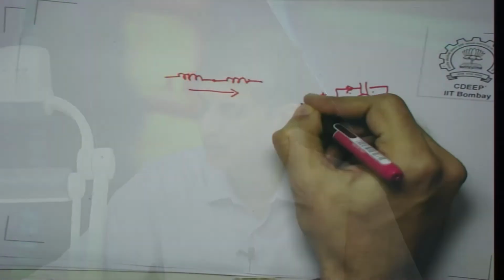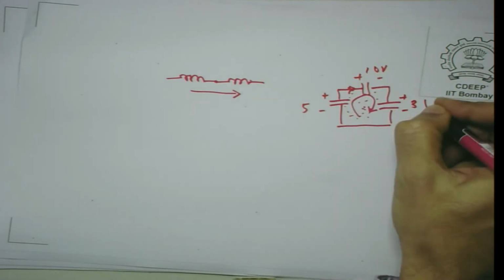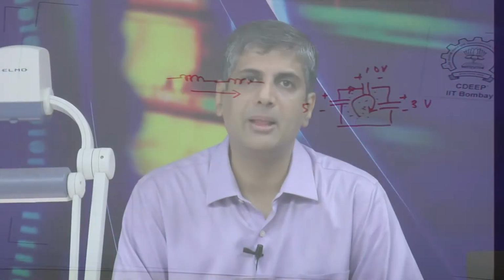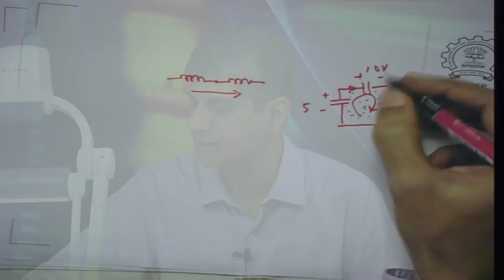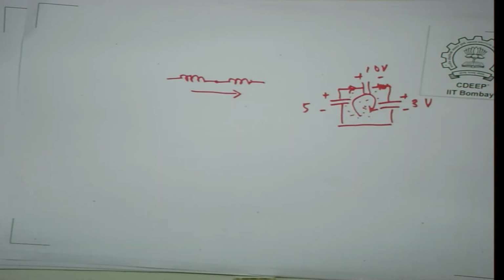For example, if this is 5 volts, this is 10 volts and this is 3 volts, you end up with an inconsistency, it does not follow KVL. So, this is prohibited, but in real life if you do this, luckily there are a lot of non-idealities, like, as I mentioned, the loop inductance, the resistance of the wires and so on. So, that will save you in some ways.